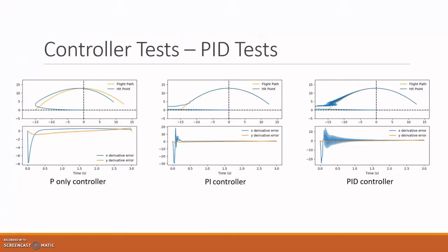When determining which parameters of the PID equation were necessary, we ran three tests: one with a P-only controller, one with a PI controller, and one with a full PID controller. The P-only controller had a smooth arc, but left a lot of offset between our process variable and our set point. The PID controller tracked it pretty well, but had a lot of oscillations, which we don't want in order to calculate when our process variable gets close enough to the set point to technically shoot it.